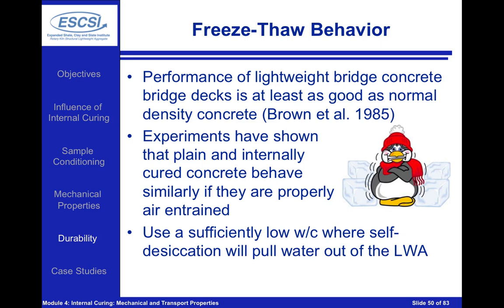And the reason for this is because at a sufficiently low water to cement ratio, chemical shrinkage is going to occur that's going to lead to self-desiccation, which will actually pull the water out of the lightweight aggregates to hydrate more and more of the paste. As it pulls the water out of those lightweight aggregates, they're going to be left as vapor-filled spaces, and it's going to be very, very difficult to fill those vapor-filled spaces back in.